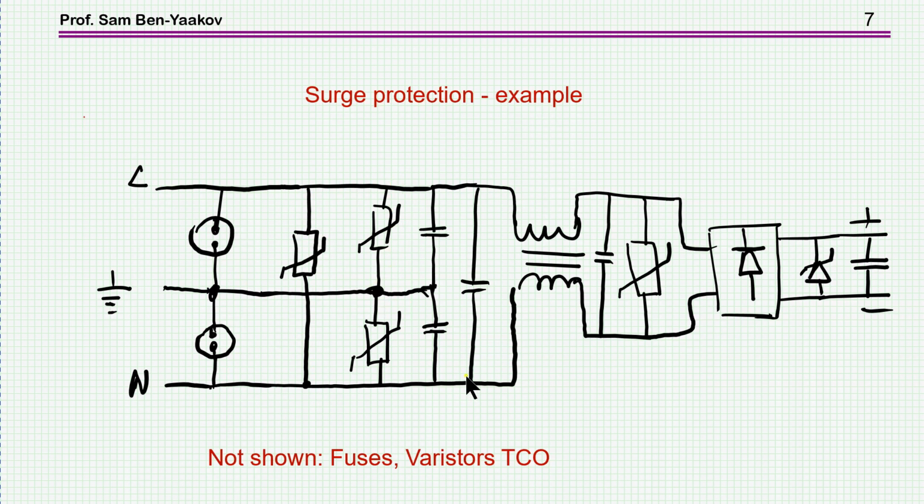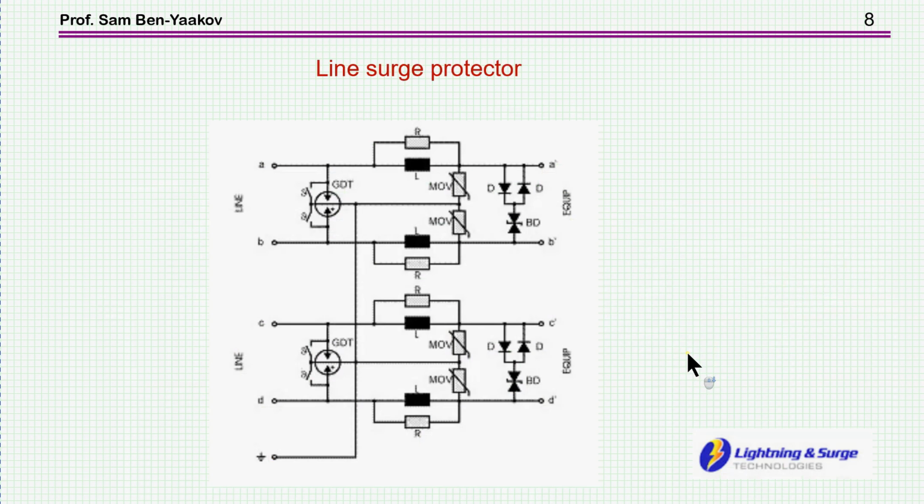This is just an EMI filter, and then we have here the varistor, which is protecting this side, and it has nicely this impedance as the attenuation. So this is a very good protection here. And then finally we can have a TVS, the output, say, of a rectifier against spikes of high voltage. So this is just an illustration of the use of these devices.